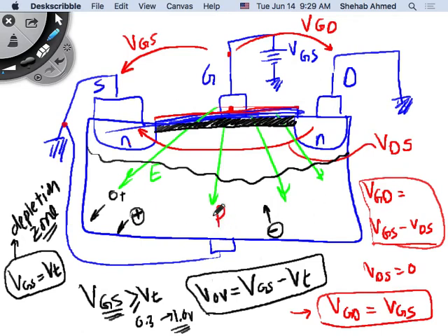In this situation, it controls it on this side and this side. Why? Because VGS is equal to VGD, right? Since VGS is equal to VGD, then I have an electric field here that is able to create a certain over voltage in this zone. And that's due to VGS. And VGS now is greater than VT by a certain amount called over voltage. Similarly, on this side, I have VGD. This VGD is what caused the electric field on this side as well, right?